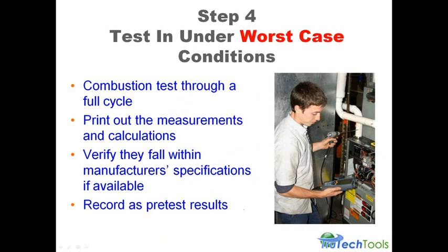It could be indicative of a rough light off. It could be a burner issue, but for the most part, you've got an igniter on one side of the burner and a flame rod on the other side. It ignites on one end and has to work its way across. There's going to be some unburned gas that lights a split second behind the first burner lighting. All right? That spike CO reading is pretty much meaningless to 99% of the guys in the industry.